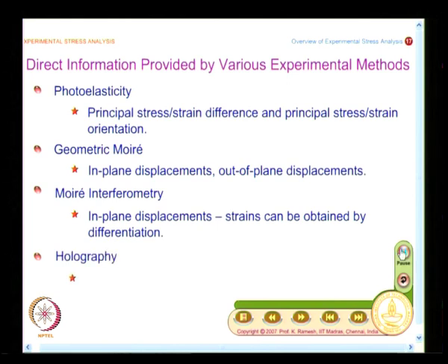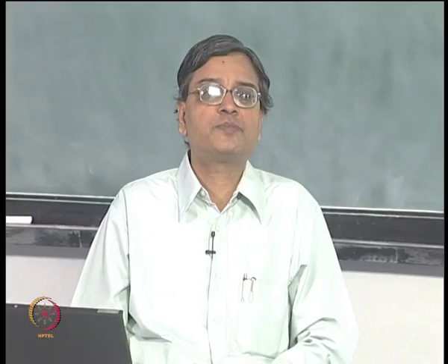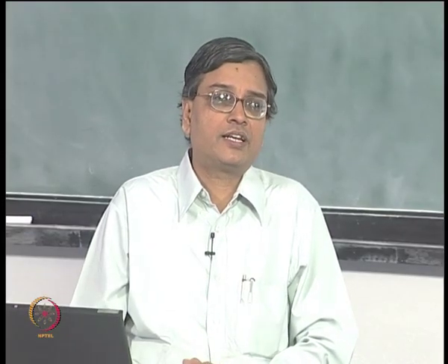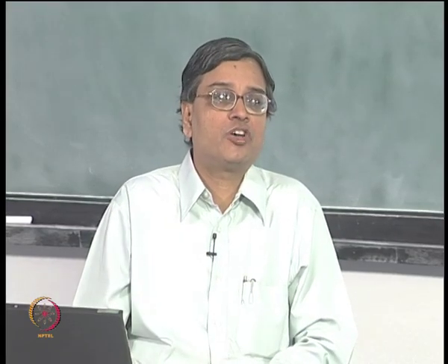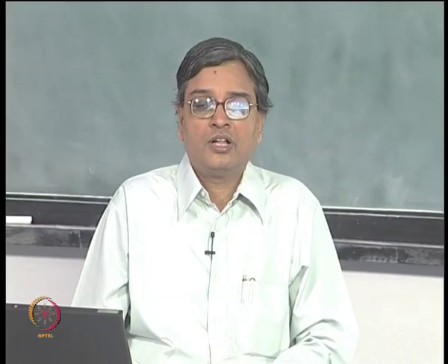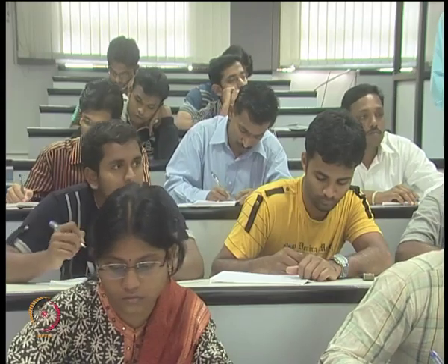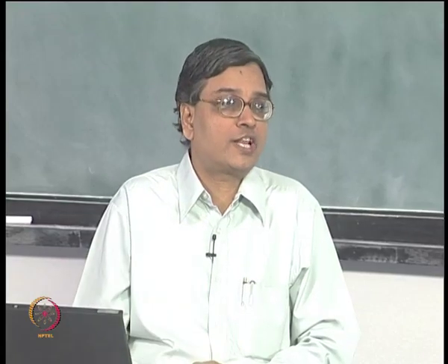And you have holography, and essentially it gives a displacement vector, and you all know it as a security device, but from a stress analysis point of view, it is a displacement vector and very attractive for out of plane displacement. In fact, in the early days when they were developing turbine blades, the vibration modes of turbine blades were recorded by holography, and it was very revealing. Holography is very sensitive as well, and the amount of effort that you need to do holography is much more than you do an experiment using photoelasticity.